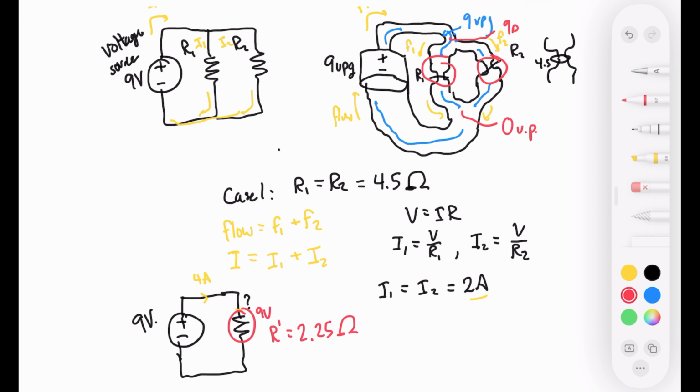Now, we started with 2 resistors that were larger and we got one that was smaller. And if you take a moment to think about this, I think this actually makes sense. Basically what happens is this water has 2 paths it can possibly take, and it divides itself among each of them. So the overall resistance that we see from this entire system should be less than either one individually, because even if one of these was really, really, really high, it could always take the smaller one and then eventually go, maybe some would go through this other one.